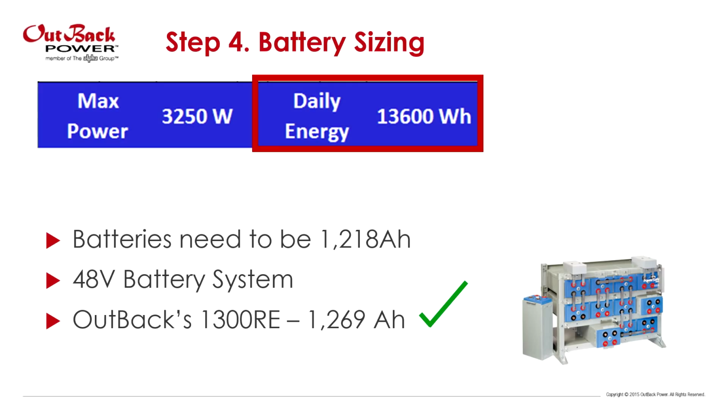If you were to discharge your batteries in 24 hours, you're going to have less capacity. So you could use the 24 number or the 20 number. It's just going to be more conservative. But if you wanted to use the right number, you could use the calculation. And remember, this is percent depth of discharge, so that would be your 50% in both these cases.